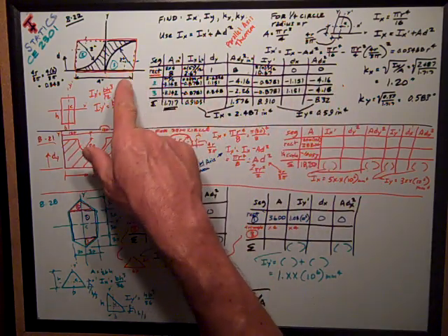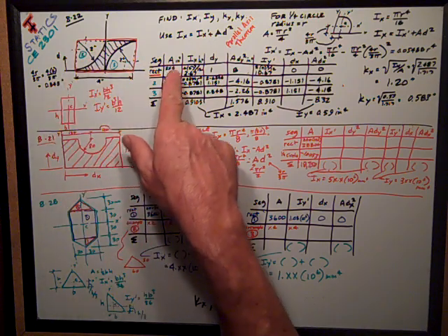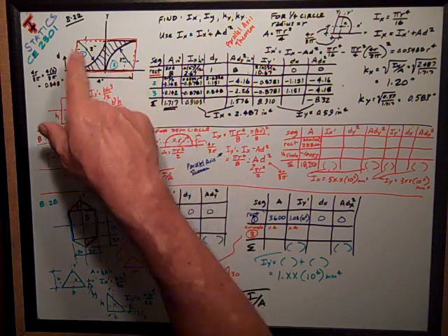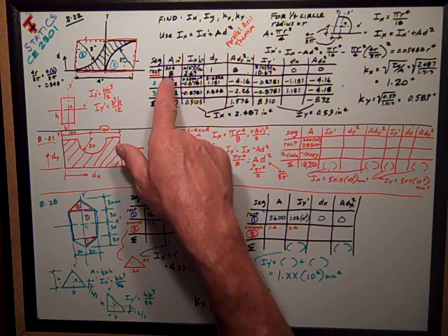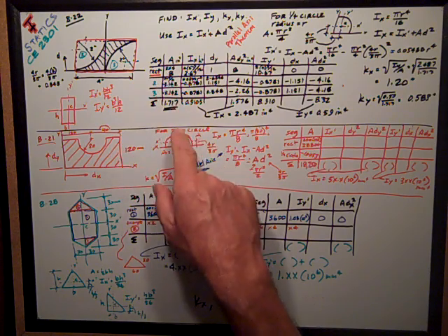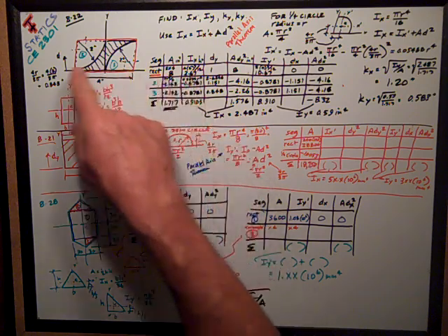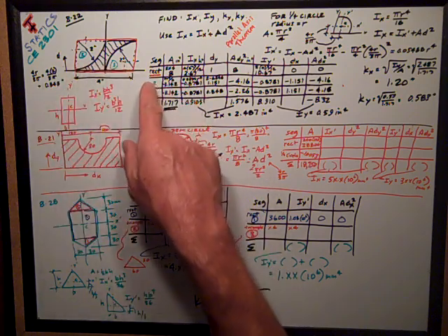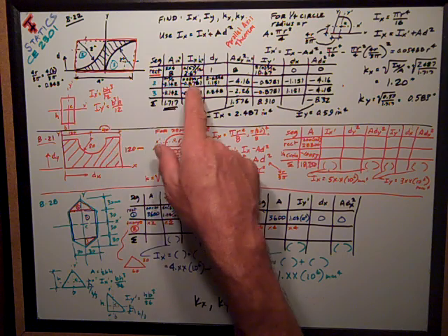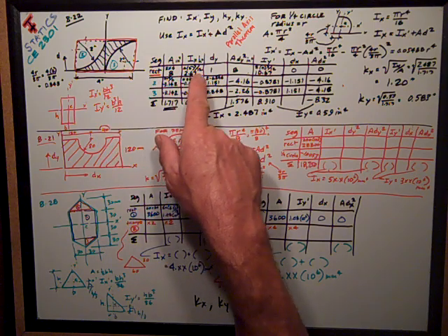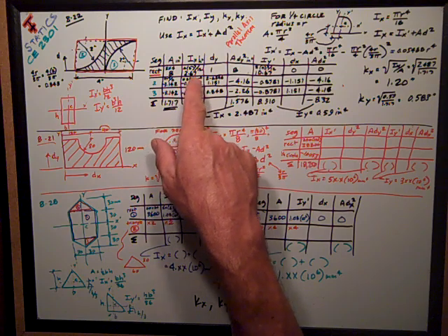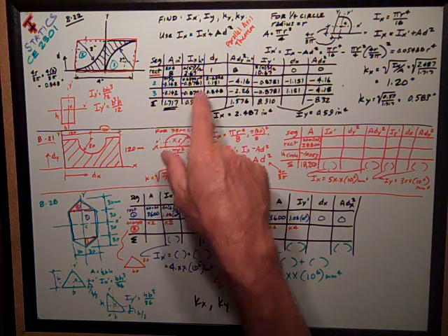Divide it into the segments of the rectangle, which is positive, which I've outlined in red, positive area of 2 by 4, so it's 8 square inches. Its moment of inertia about its own x-axis, x prime axis, through its centroid is 4 times 2 cubed over 12, 2.67 inches to the 4th.